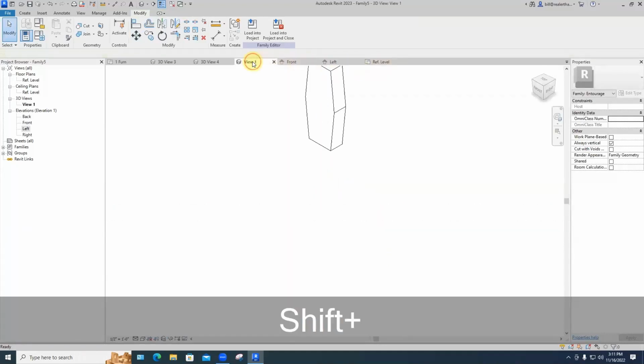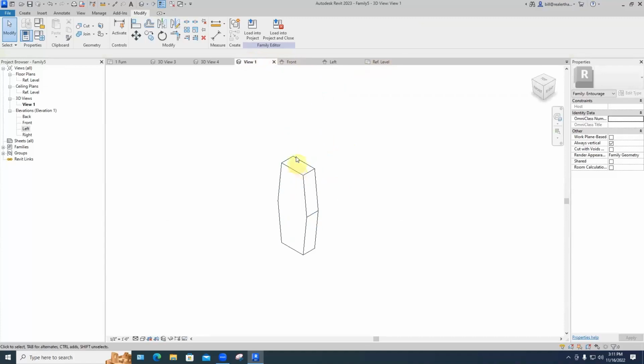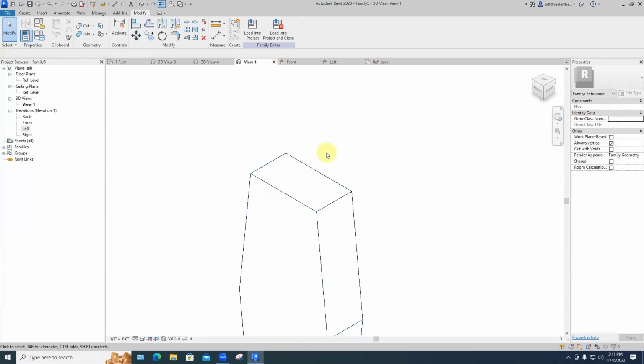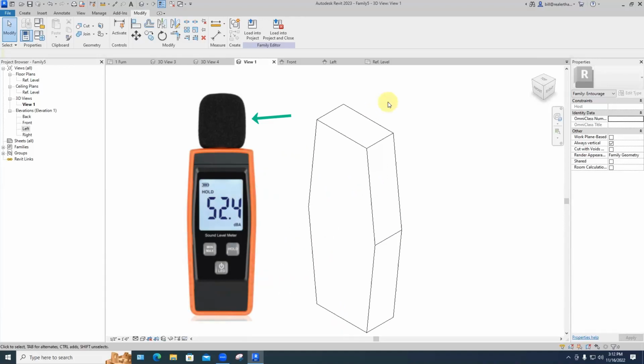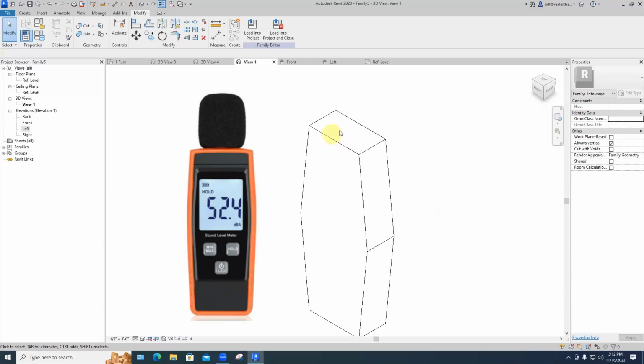So there's a little guy, cute, cute, cute. So how do I draw this on top of that? It's not a void. I need to add the microphone shield here on the top. Well, it's actually sort of an interesting shape. If I want to get this roundy stuff, that really needs to be part of a revolve. So let's say it's 1 inch high and 1 inch across. I'll make it down on the ground. We can move it around. We should make it right here.